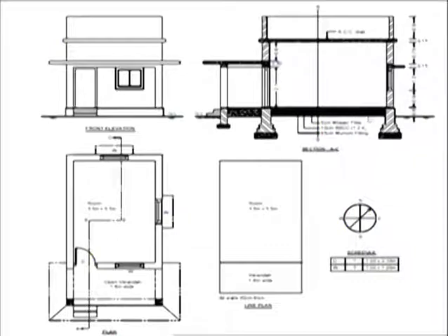So we have to calculate what will be the thickness of the soil filling here. So 2.5 centimeter thickness of the flooring, 2.5 centimeter the cement mortar, that is the 5 centimeter, then 15 centimeter concreting. So 15 plus 5 is equal to 20. So 20 centimeter is fixed, and total height is 60 centimeter. So soil filling will be equal to 60 minus 20, that is equal to 40 centimeter. So 40 centimeter soil filling will be there.